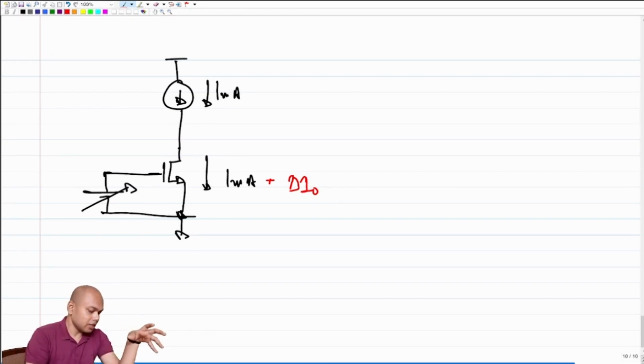The transistor VGS, the transistor overdrive changed, right? So if I had the ability to change the VGS also, then it's possible that I could have changed the capacity of the transistor to sink in different values of current, right?